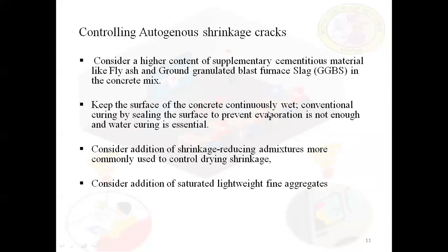Next, keep the concrete surface continuously wet. Conventional curing by sealing the surface to prevent evaporation is not enough, and water curing is essential. That means you have to do regular water curing, so we avoid the loss of water. Next, consider addition of shrinkage reducing admixture. That means we have to use some shrinkage reducing admixtures and lightweight fine aggregates. Once again, by using this, we can avoid the autogenous shrinkage cracks.